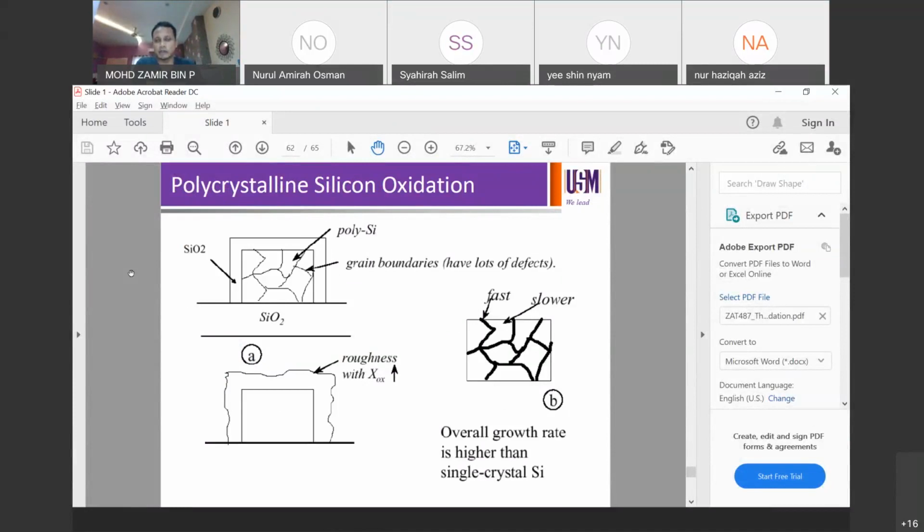The size of the grains can be as small as microns, or it can be as big as you like. But typically, if you talk about a very thin layer, then it should be micron or even nanometers. If you talk about bulk silicon, then the grain can actually be millimeter size, or in fact centimeter size. When I worked on my PhD last time, I worked on polycrystalline silicon on glass. The thickness of the crystalline silicon is about 10 microns, so that's about our hair divided by 10.